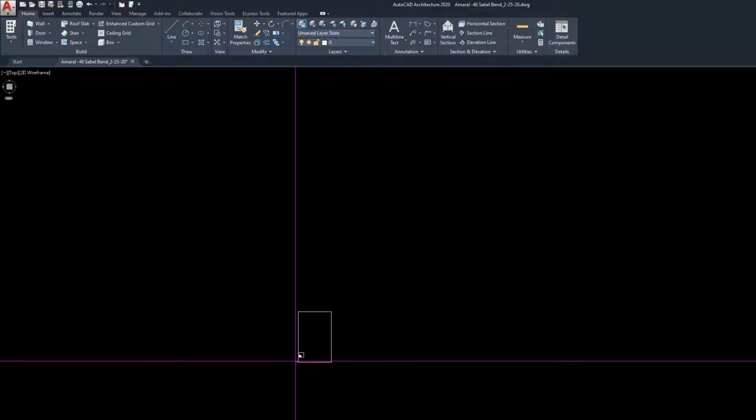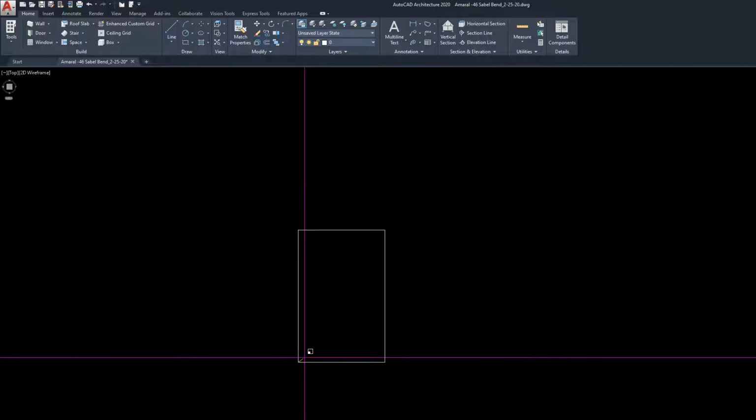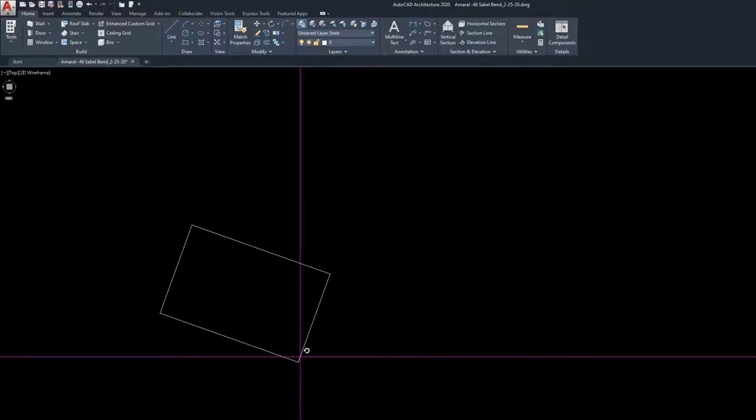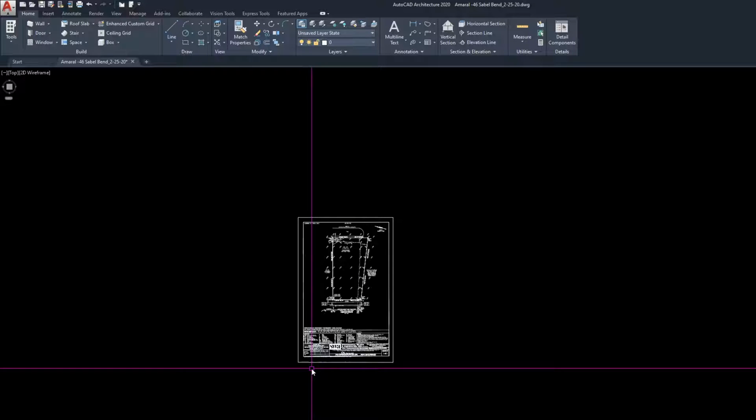If you have a multiple page document, you can type in the command line what page you want inserted. You can only insert one page at a time. So as I said, the default is 1, so we just hit enter. Pick a point on the screen and you can scale it just like this. Obviously it's not any known scale, so just pick something and click, and you can change the orientation as well. We're just going to hit enter, and again default goes back to straight up and down 90 degrees.